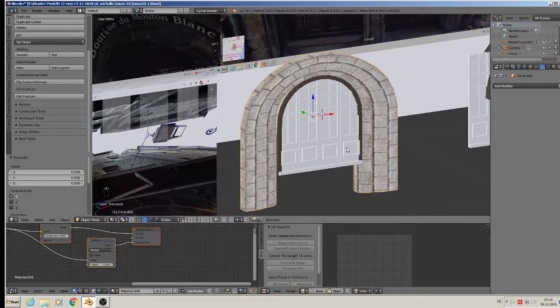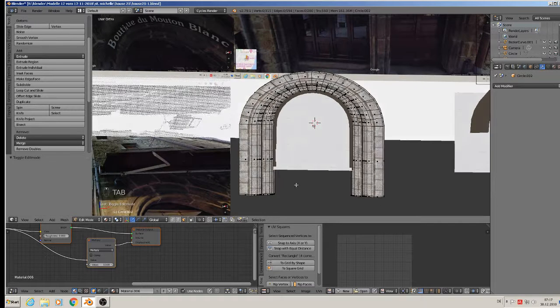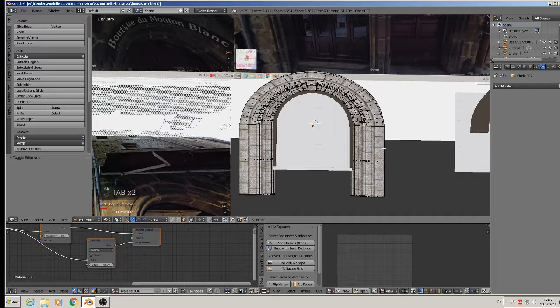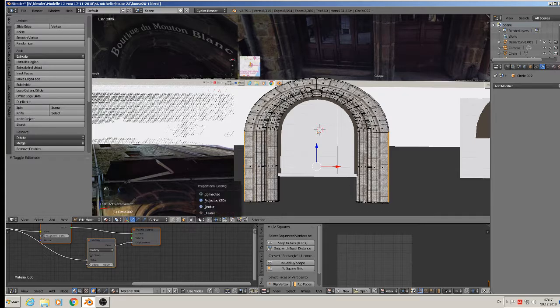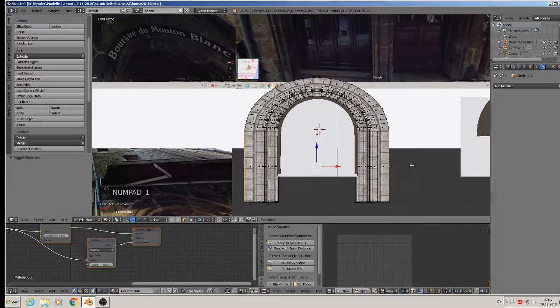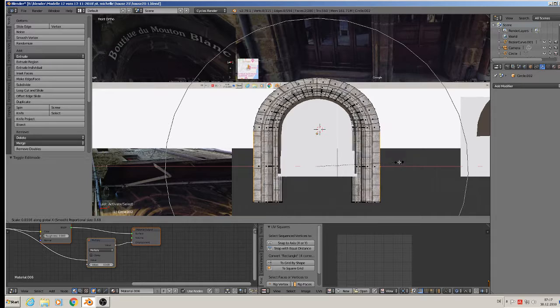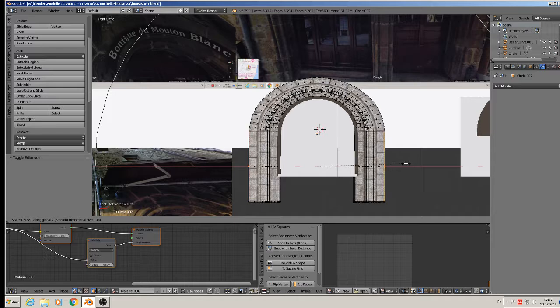That looks better, but not optimum. So we have to bring that here more up, and it's all in all too fat. So I will take here these sides and take here the proportional editing connected and scale X. Now I can roll the middle mouse to get the influence type, and now I can handle how much that influences my whole object.